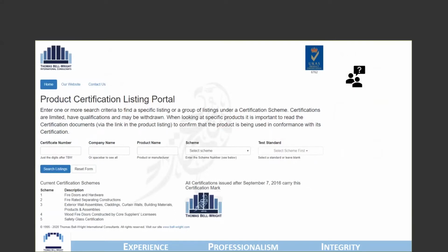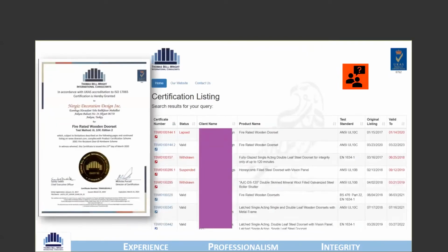The certification and listing as a concept has an independent third-party body who will create a link between the sample that gets tested at the manufacturing location which is defined, and also by means of an audit scenario, they will ensure that the manufacturing location which is listed on the certificate, which is available for anyone to verify online by going to the certification directory, is supplying a given material which will comply to given properties.